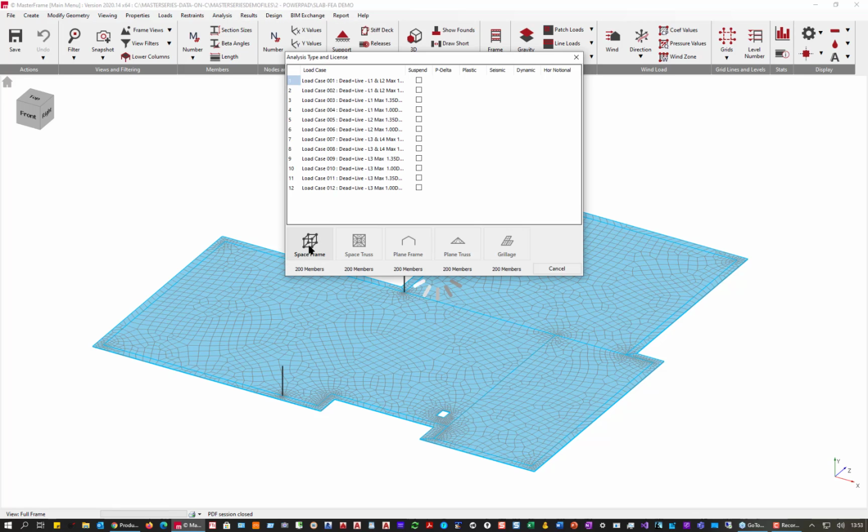in the system. So this has got the subgrade modulus for your soil properties, because this is a raft, and therefore with subgrade modulus you're doing a more iterative process in your analysis.